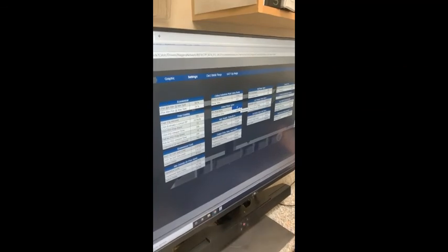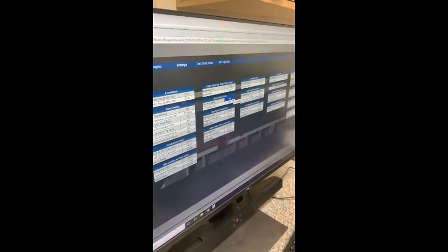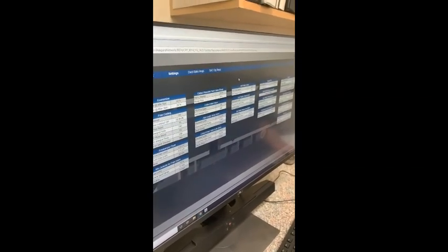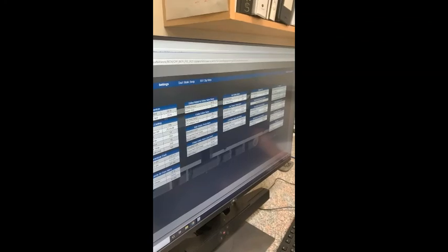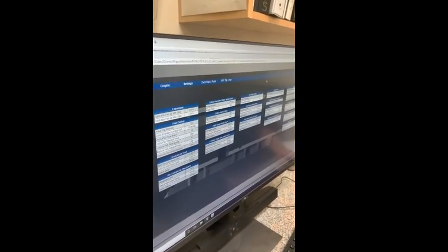From here, you can actually go through and reset the PID loops for any of those. They should be relatively tuned. They shouldn't really need adjusting. Is that self-tune? It's not a self-tune. You actually set the proportional or the integral right here.